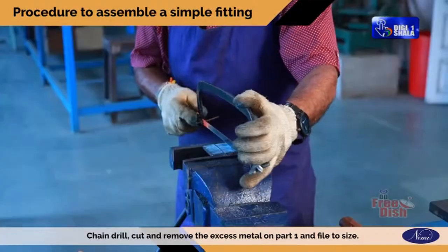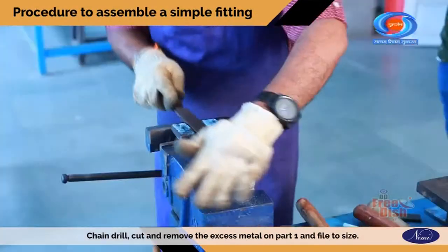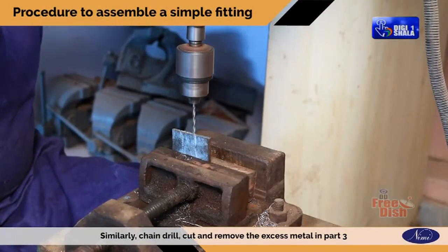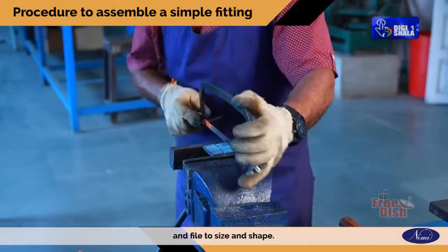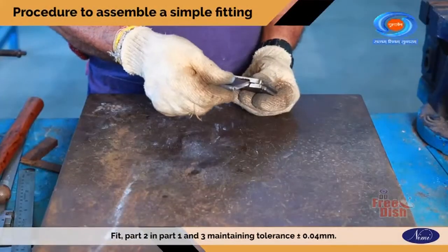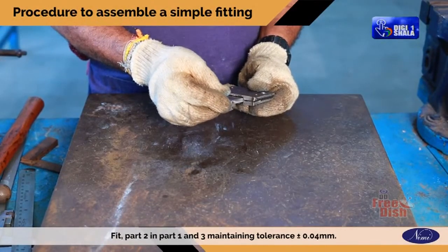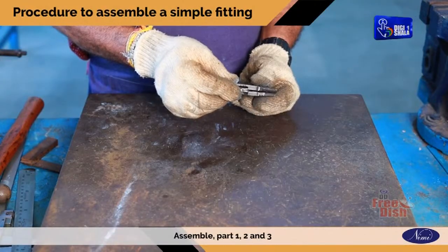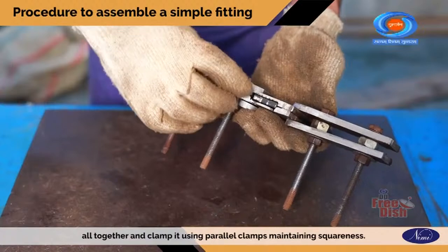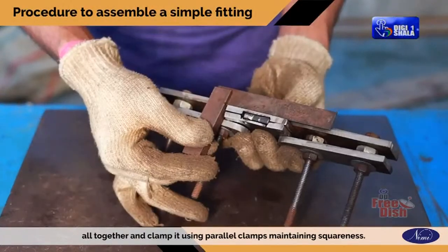Chain drill, cut and remove the excess metal on part 1 and file to size. Similarly, chain drill, cut and remove the excess metal in part 3 and file to size and shape. Fit part 2 in part 1 and 3, maintaining tolerance plus or minus 0.04 mm. Assemble part 1, 2 and 3 all together and clamp it using parallel clamps maintaining squareness.